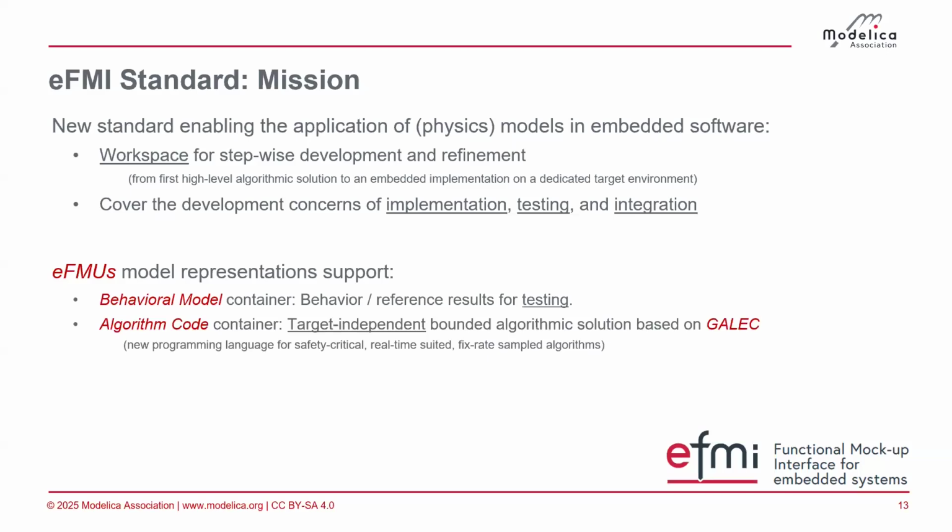That essentially is a target-independent bounded algorithmic solution based on GALEC. GALEC is a new language in the eFMI standard for safety-critical real-time fixed-rate sampling algorithms. The idea here is that your modeling environment, given your model, tries to transform it into a GALEC program. This may fail, this may not work, the model is too complex, but if it works, then you get all these guarantees. And you know, this is really suited for embedded. We didn't talk about the hardware yet. Maybe your hardware is not powerful enough to run it, but you know it has a bounded execution time, and you know it has a fixed upper bound for the memory consumption.